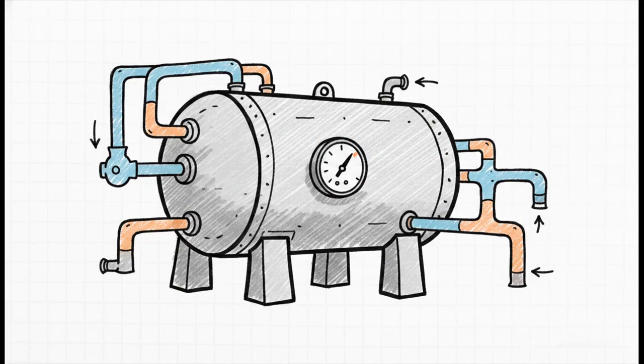Now, ASME also handles the equipment that generates all that pressure, because while piping transports the pressure, the vessels actually hold it. To handle this, ASME has an 11-section boiler and pressure vessel code, often called the BPVC. Out of all 11 sections, Section 8 is the one specifically dedicated to the rules for pressure vessels. It's an absolutely essential companion piece to the piping codes for any process engineer.